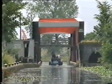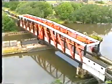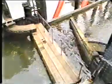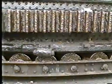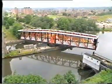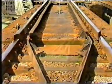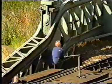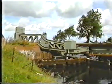In a symmetrical swing bridge, equilibrium is established naturally. This symmetry is a necessity in this aqueduct swing bridge. Symmetry, because changing water level and the possibility of leaks must also be taken into account. In these two unusual asymmetric swing bridges, two counterweights keep the bridge in equilibrium. One counterweight in the lateral direction, the other in the longitudinal direction.